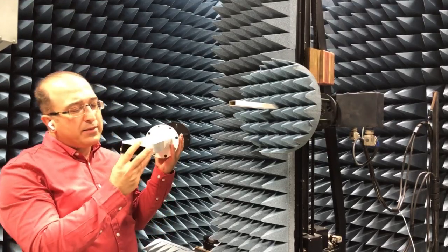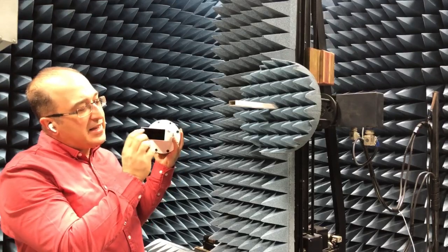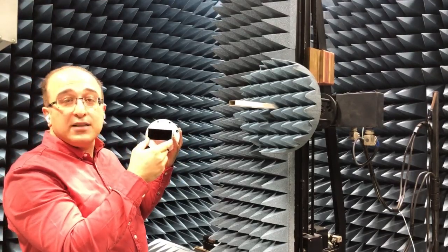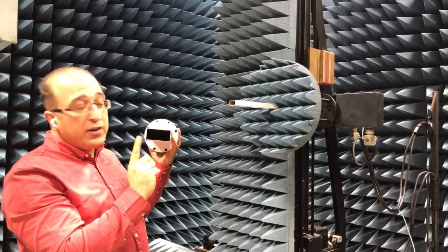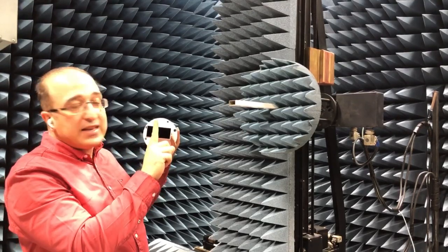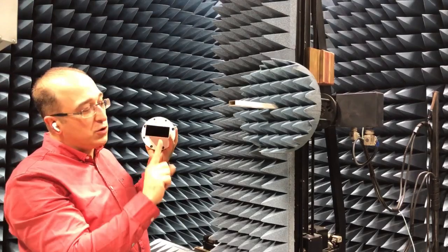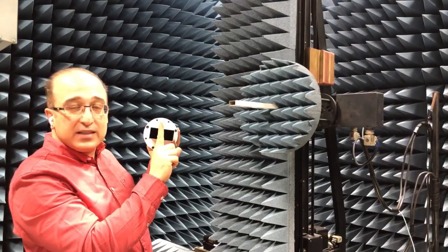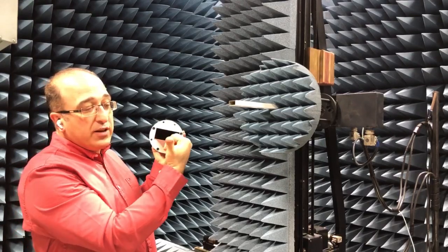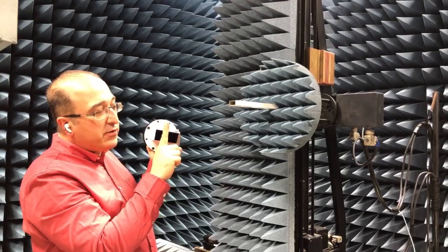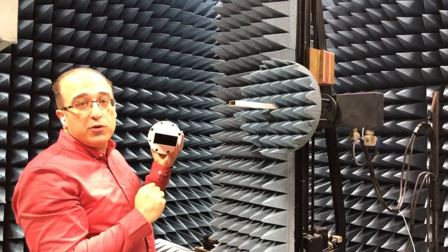Just before going, let me emphasize again that as you see this waveguide, it has a narrow wall and it has a wide wall. So in the fundamental mode, the electric field is along the narrow wall. So this is going to be the polarization. It's going to be along the narrow wall. This is your electric field. So the wave is traveling, let's say, toward you. So this is the electric field, and then we're going to talk about the magnetic field too.